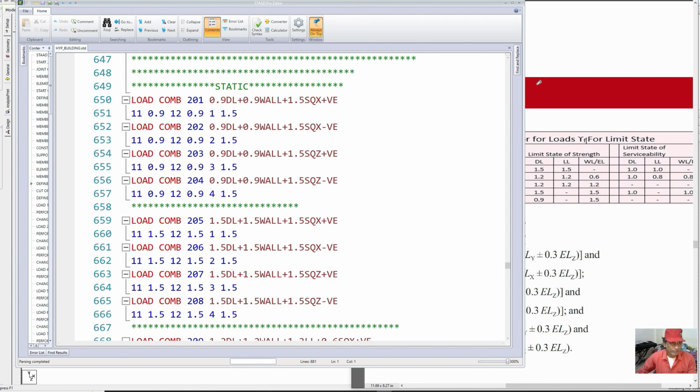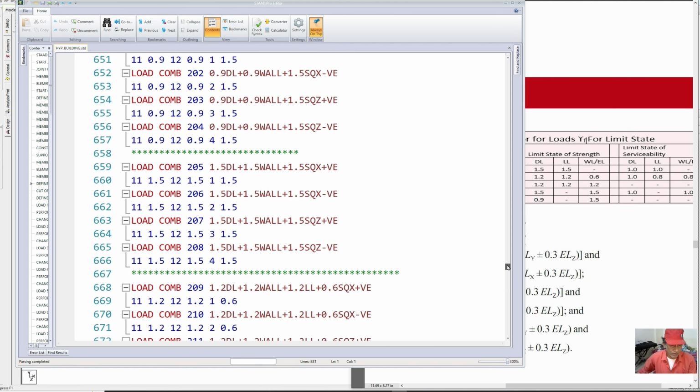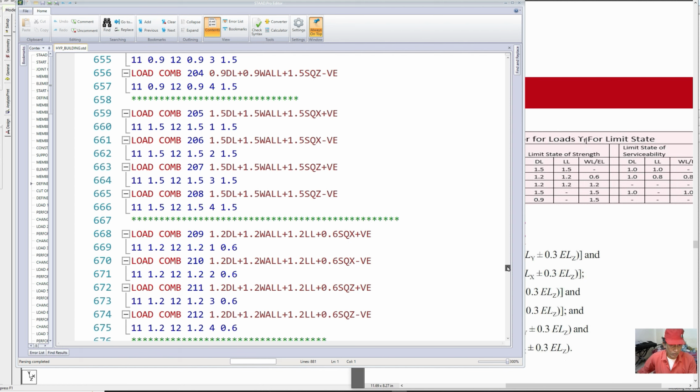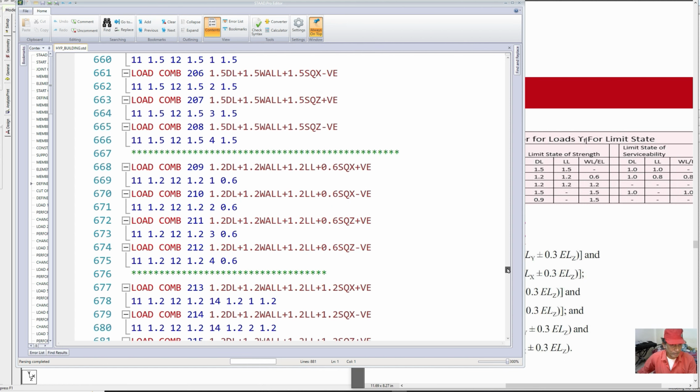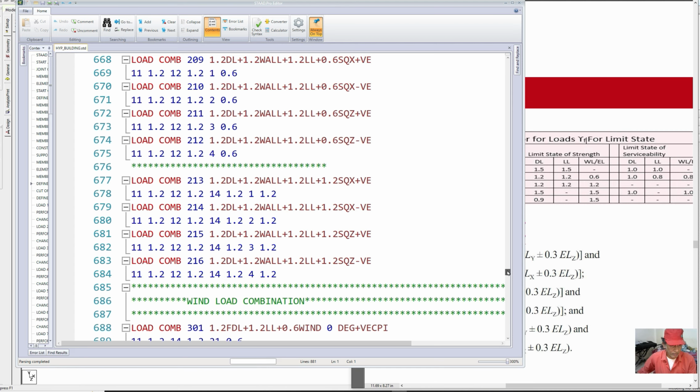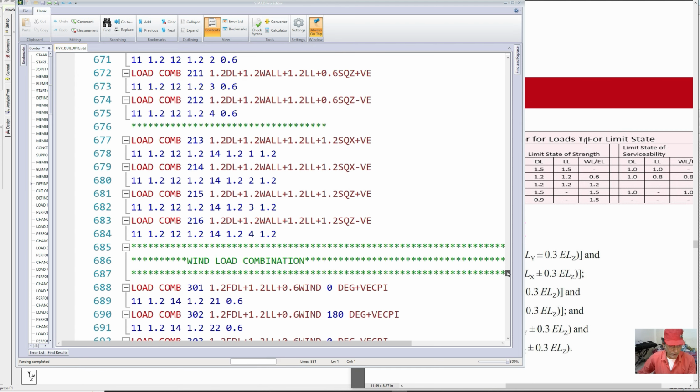Then we have defined the same load combinations with static load cases. In static load cases, obviously we do not have this load in Y directions. So it has not been implemented in STAAD Pro V8i E-Connect edition. Probably they have included this, but we have already included it in dynamic analysis. So this will suffice the requirement for the design.